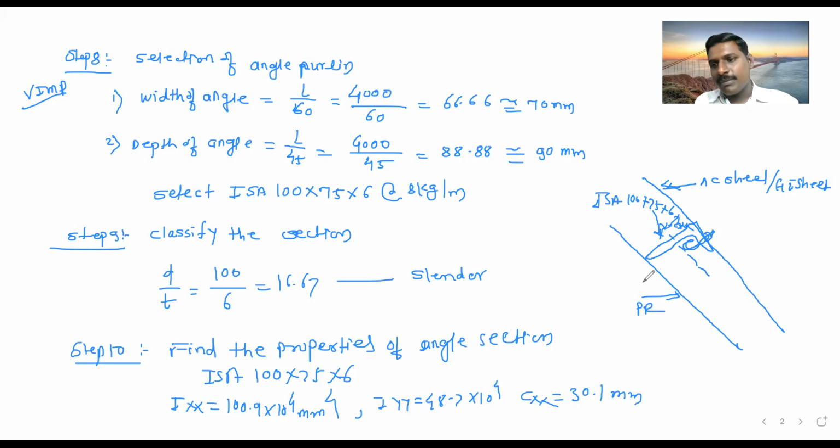It means on the principal rafter, the purlin is rested. On the purlin, seats will be there. The seats are connected with the purlin by this hook. So how do we have to place this purlin? We have to place it like this. Generally, the depth is kept vertical here.